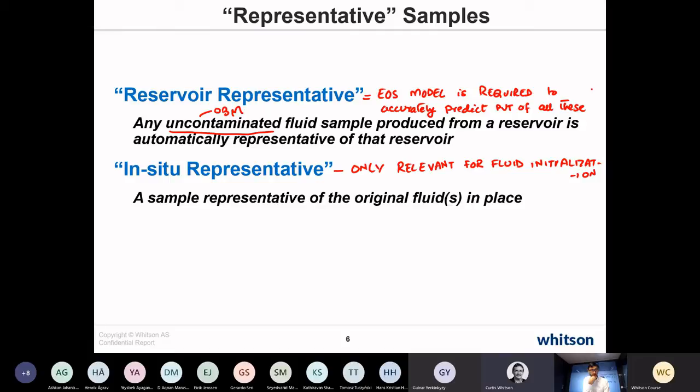Okay, that's in a perfect world. And open hole formation test samples with oil-based mud contamination can and should always be used to calculate the decontaminated composition for fluid initialization, whether it's 2%, 40%. You should decontaminate the composition and try to use that in your mapping of in situ fluids. Those are the two general guidelines that we operate with.